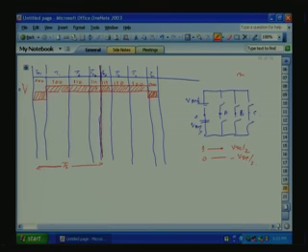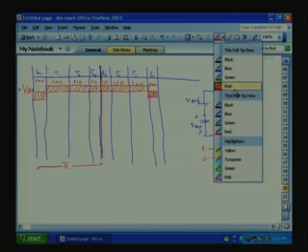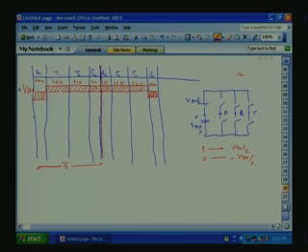Let us draw this, this is VA0. Now let us draw VB0. B, let us take blue. So B again will start with 0. 1 0 0 means B is also 0 here during the T1 period. Now here B goes positive, that is 1, VDC by 2.